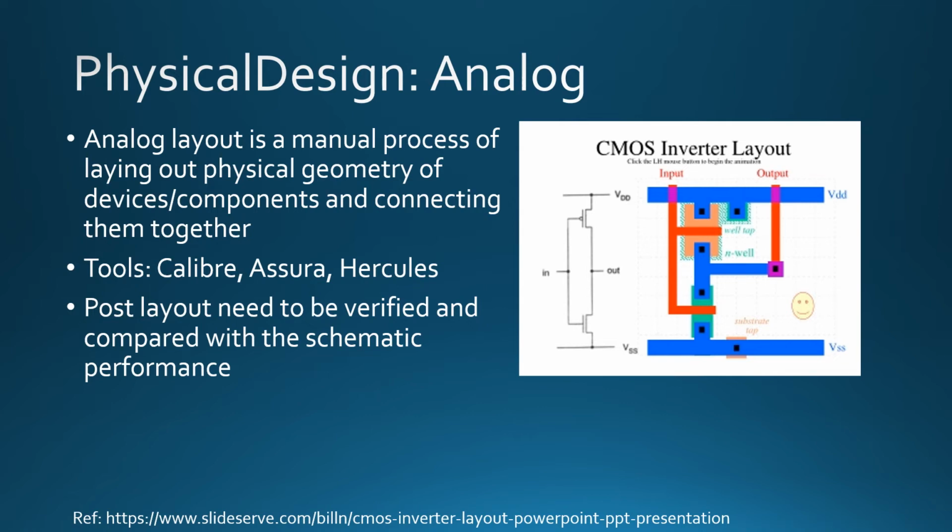Basically, on the right side, you can see a schematic of an inverter and how it is laid out in the layout. You can instantiate two transistors, NMOS and PMOS, from the technology library. As a PCell, it will mostly be already available from the technology library, so you can get the NMOS and PMOS as already built layout PCells.